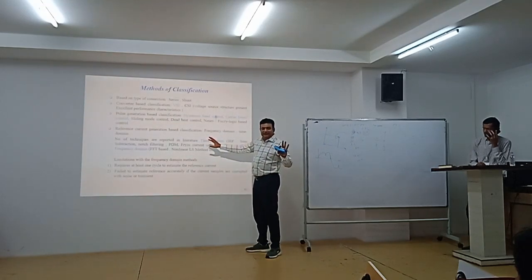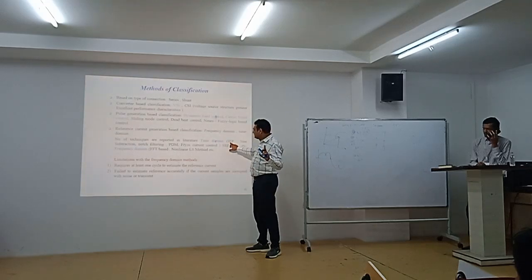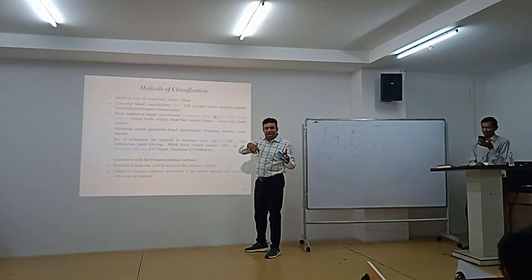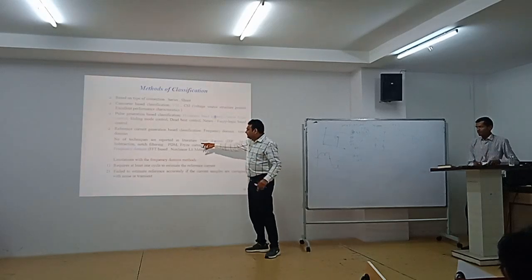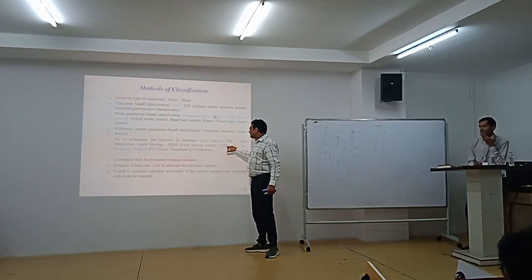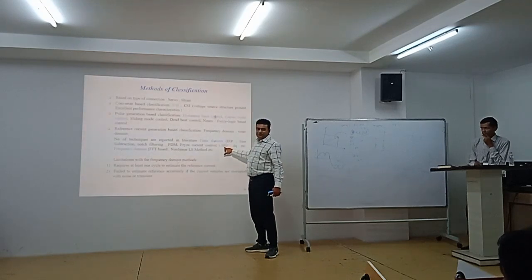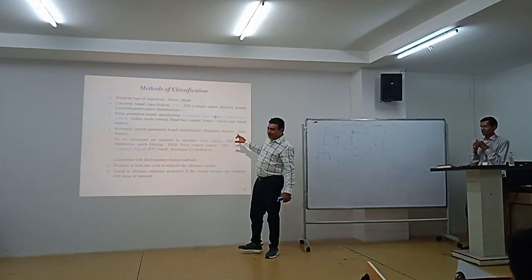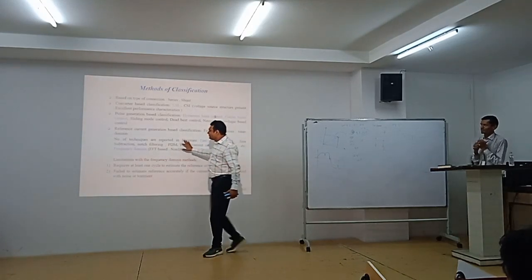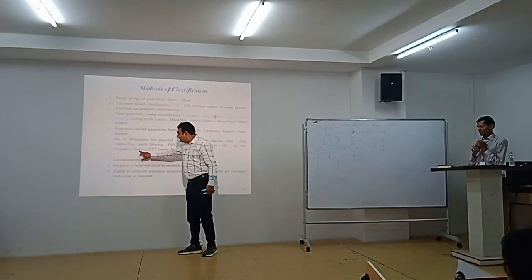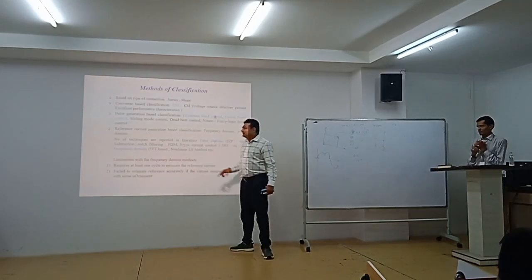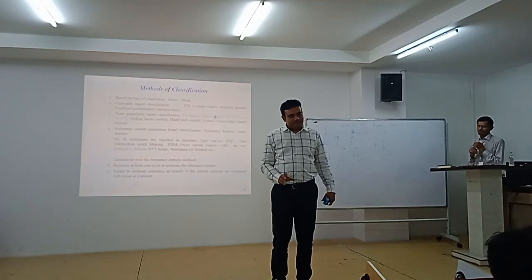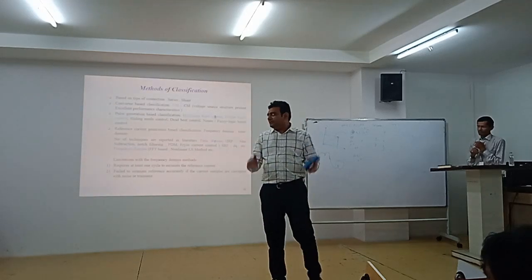There are different current techniques for this as well. Instantaneous reactive power theory, sine wave subtraction, notch filtering, that is, it notches out 50 Hz, PWM free current control, and synchronous reference control, synchronous reference frame theory, and DQ control, right? So these are all time domain techniques. In frequency domain we can go for FFT based or least square method, right, where we can go into the detail.